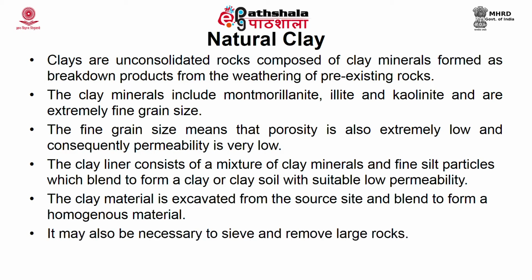It is always necessary that when you collect the material from the landfill site or from the surrounding area, the material has to be sieved, so that the large rock particles are removed. Why should the rock particles be removed? A rock will puncture or tear the polymer material which has to be spread over this natural clay.